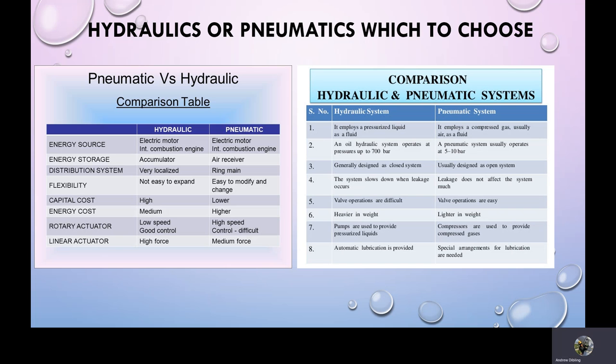Hydraulic system, of course, is a closed system. The fluid is returned to the reservoir. The fluid is contained within the system, whereas in a pneumatic system, it's an open system. Once the gas is used, it's vented out to atmosphere.